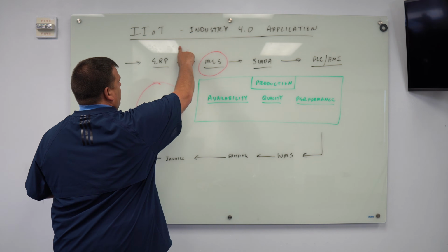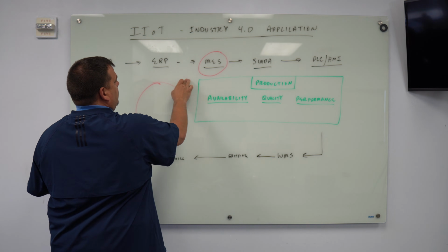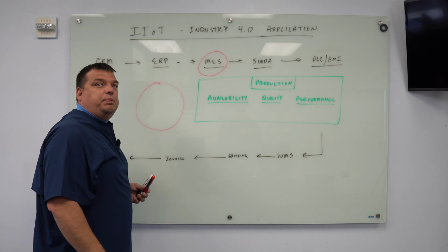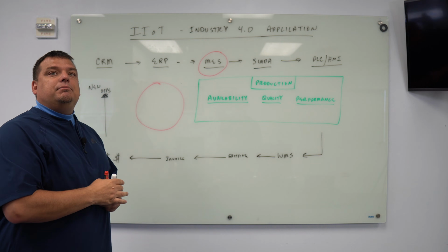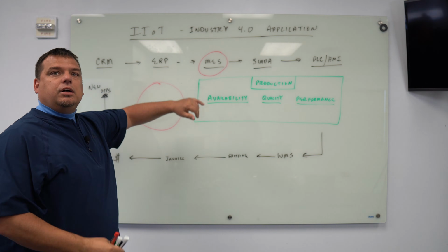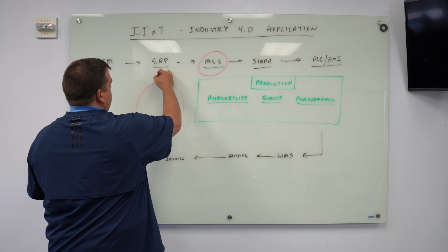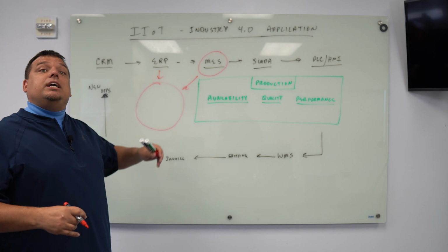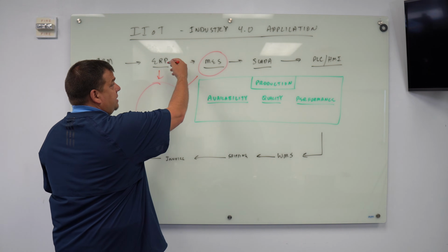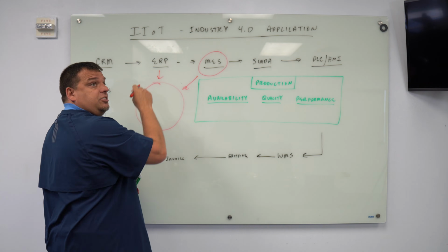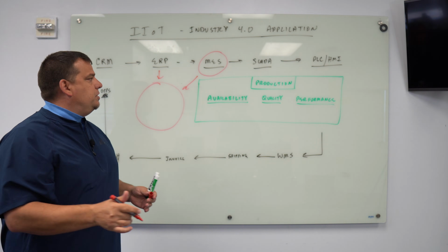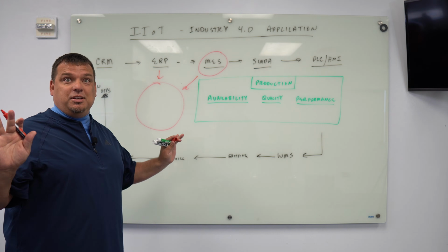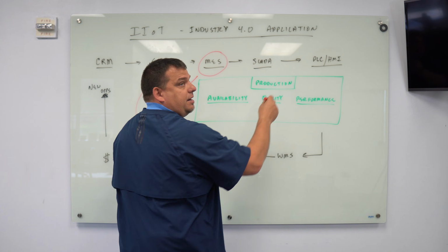So anyway, let's move this. So what happens when I upgrade my ERP system? I've got an explicit connection between ERP and MES, and I upgrade my ERP system. I've got to redo those connections. But if the ERP system and the MES publish into a unified namespace and I make an upgrade to the ERP system, do I have to reestablish this connection? No. When I do the installation of the new ERP system, all I do is configure the area within the namespace it has to publish into, right? Very simple, easy stuff. Same thing, MES, SCADA, PLC, HMI.